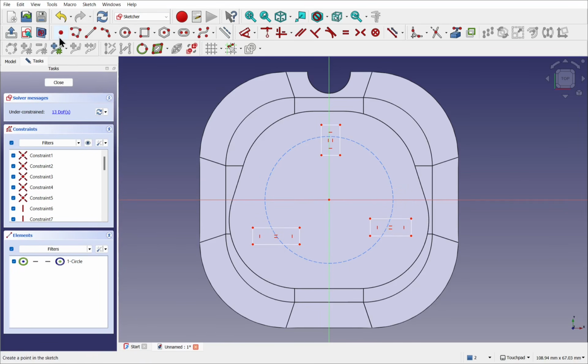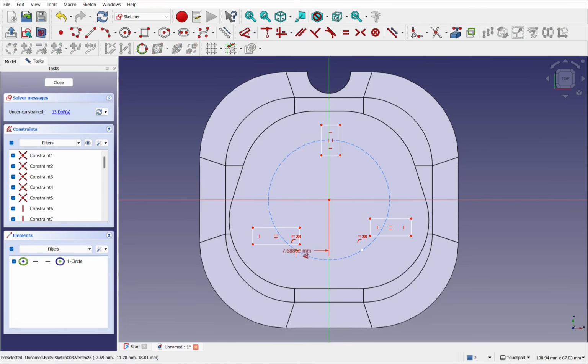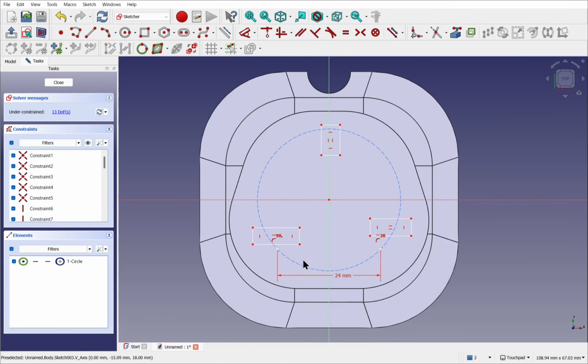Let's move this one down. And I'm going to place a point in here. Connect the point up to the construction geometry, placing that point on object constraint. And we'll right click to cancel and take these 2 points and place them in line with each other. Next, let's place some dimensions between the 2 points and set that to 24 millimeters. So what I'm doing is building construction to allow me to attach these two. And I'm looking to adjust this so we can easily adjust the geometry that's connected to it.